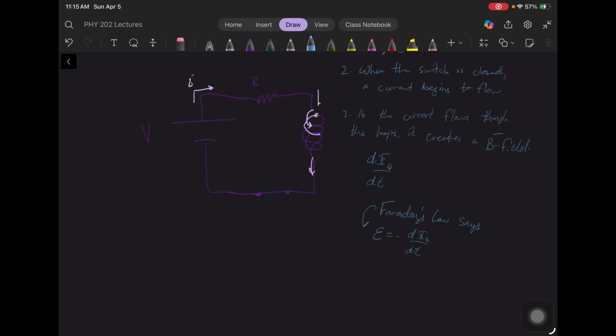Right, and then Lenz's law says, hey, this EMF is going to directly oppose everything you're doing. And so what do we get? We said if the current's going through this way, we get a magnetic field going this way. And so in order to oppose that, we want to make a magnetic field going this way. And for that to happen, we need a current that travels this way. So you may see we are at an impasse.